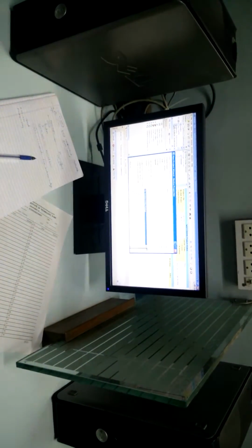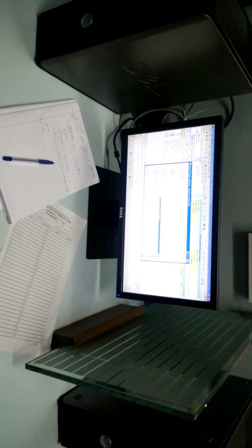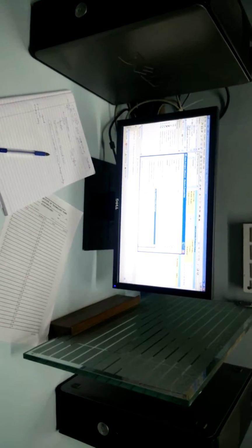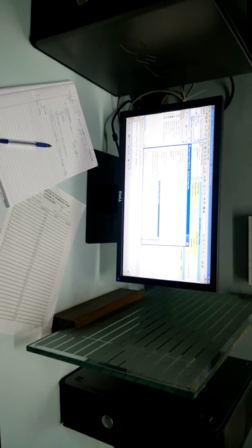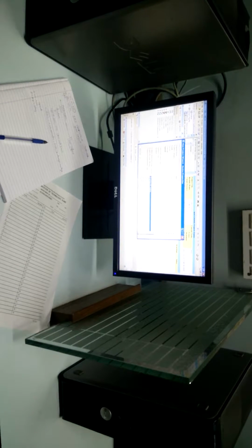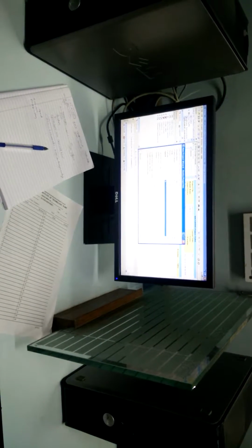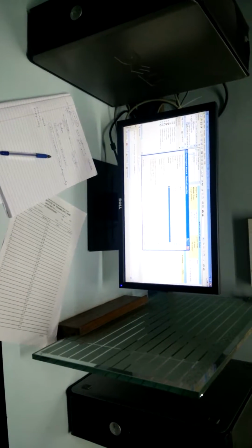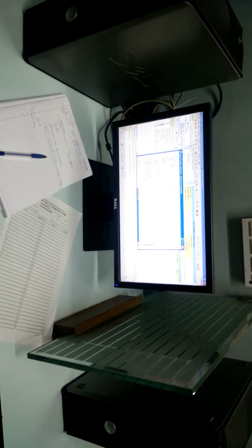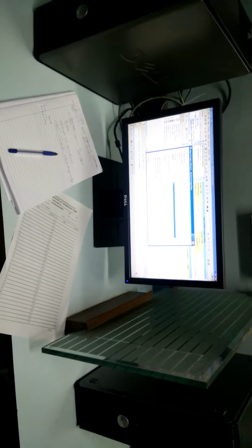Whenever both these tools are installed on a PC, they get linked at the back end, and you can use both the synthesis tool and the simulator tool. But nowadays Xilinx has introduced its own simulator tool, ISim, so there is no need to purchase a separate simulator. Other simulator tools are ModelSim from Mentor Graphics, and there are various other tools also.